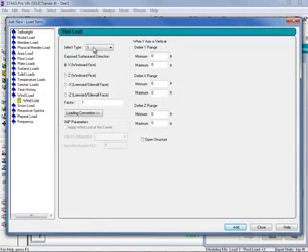For the leeward wind load, that corresponds to our loading type 2. We will select -X and say it's a leeward load, and we'll keep the factor set to 1.0, again for the positive direction. Then we will click Add, and we'll add 2 more load items for the sidewalls. Our sidewall definition is number 3 for our X direction.